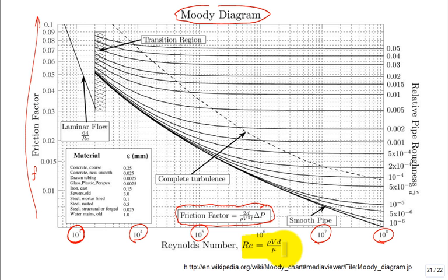Now the friction factor, y-axis. Always takes us a little time to work through that. Do you like this definition of the friction factor? I can't hardly read it, so let's even rewrite it maybe. If I rewrite that friction factor, he's saying that F is equal to 2 diameter divided by rho v squared L. That's my L length, diameter length, delta P.